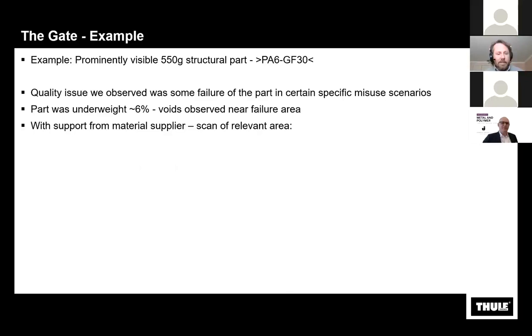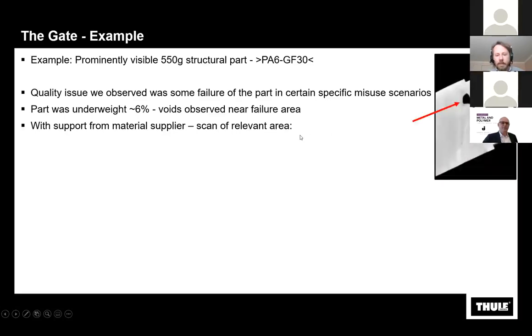Because this part was approximately 6% underweight, we knew something was amiss, and we could observe voids near the failure area. So with support from our material supplier, we did a scan of this part,